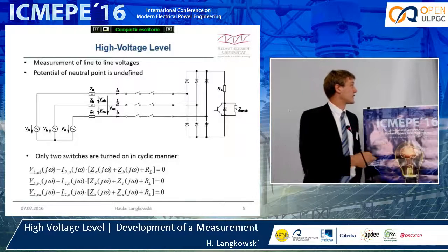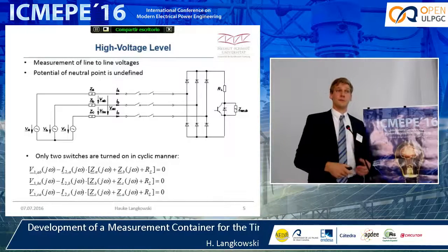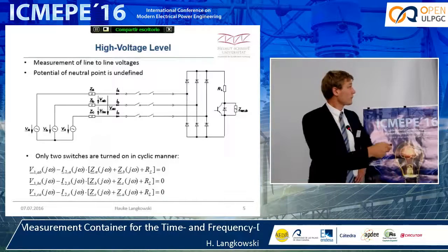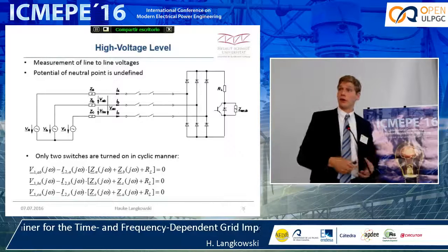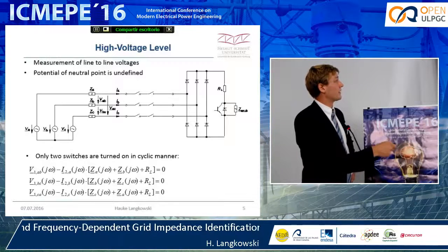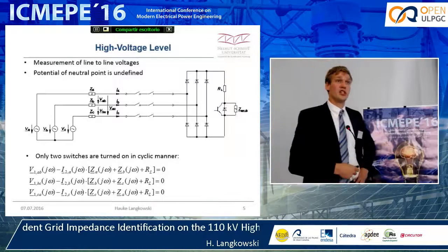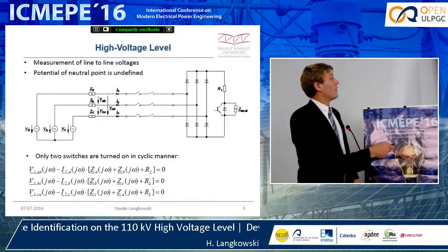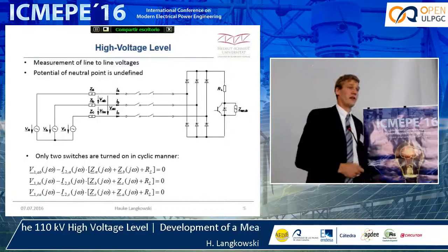You will see on the next slides that we have a power switch. The power switch can be activated in each conductor line separately, and then we have power electronics that is directly working on the 110 kV voltage level. We have a B6 diode bridge, the load resistor, and here an IGBT, of course a series connection of several IGBTs, and this IGBT is then pulsing the load resistor as on the last slide.